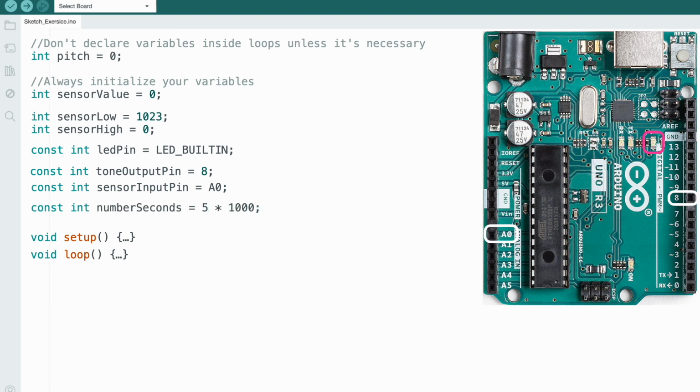So here we're looking at the number of seconds that we're going to use to keep the LED on, before we decide that the board is initialized and we turn it off. And you'll notice here it looks a little wackadoo, right? Why 5 times 1000? This really makes 5 seconds, right? There's 1,000 milliseconds in 1 second.